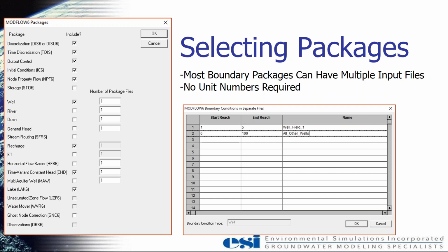So, if you're using MODFLOW 2005 in Groundwater Vistas, you have to go to the MODFLOW packages dialog, the MODFLOW 2000 packages dialog, and the MODFLOW 2005 packages dialog to assemble all the packages for your simulation. MODFLOW 6 uses far fewer package types, and so it was simple enough just to put them all in one place. So that's what I've done.